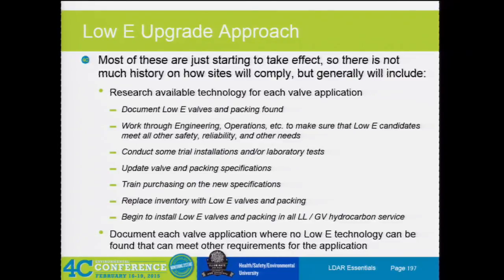So now you got to not only think of purchasing all this, you got to get your procurement people to buy off, and now they can only go purchase all this. Then you got to work with your engineering department, so when they're designing stuff, they're designing it to within the new specifications. And then you got to work with operations to go, okay, all of those non-low-E valves that we still have in stores, you can put them on water. You can put them over here on this. It's not regulated, don't care. But when you touch this line that has an LDAR tag, it's got to have this valve. So now they just got to understand a whole other level of training.